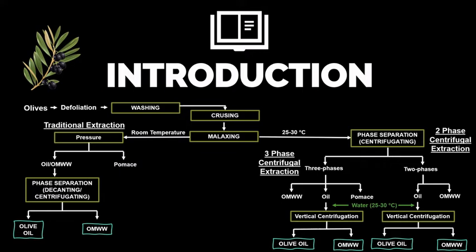The quantity of olive mill wastewaters that is generated and consequently the environmental impact depends on the method of olive oil extraction that was used. The traditional cold press method typically generates about 50% of olive mill wastewater relative to the initial weight of the olives, while the continuous centrifugation process generates 80 to 110% of olive mill wastewaters due to the permanent washing of the olive paste with warm water prior to oil separation from the paste.